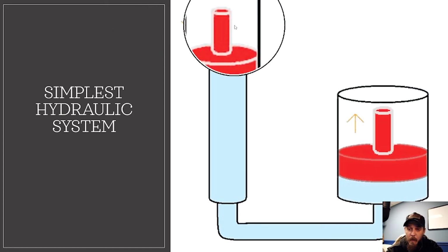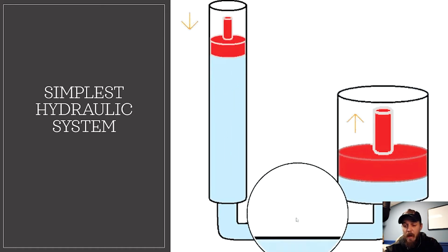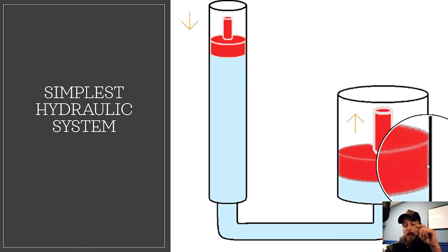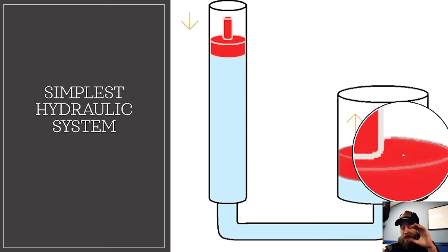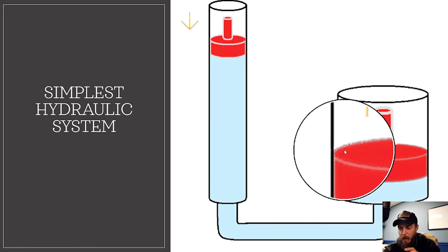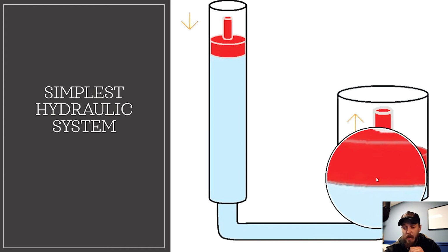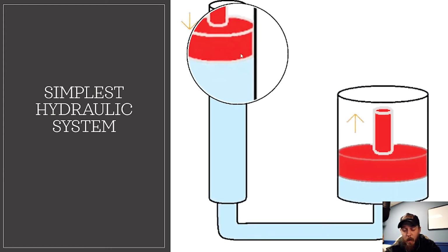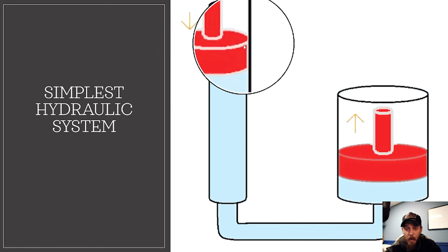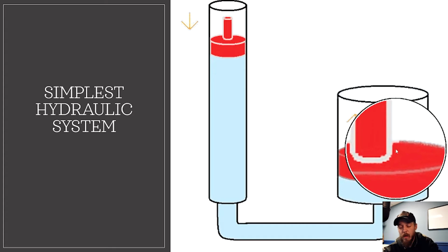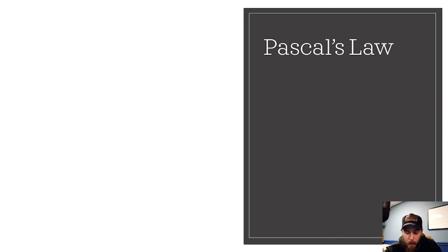Now, we may have, say, 6 inches of stroke here. Because we're going from a smaller diameter to a larger diameter, we're going to cut down our stroke. And there's math involved in that, and we'll get into how much of that we really need to understand and when it makes a difference. But suffice it to say, if we have a long stroke here, as we magnify that force, we decrease the overall stroke.